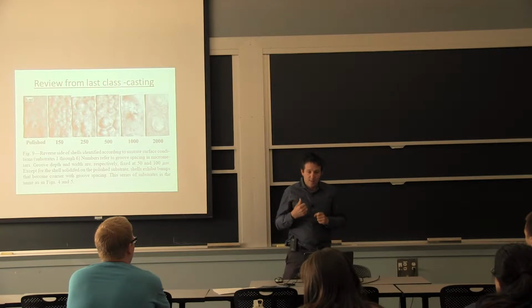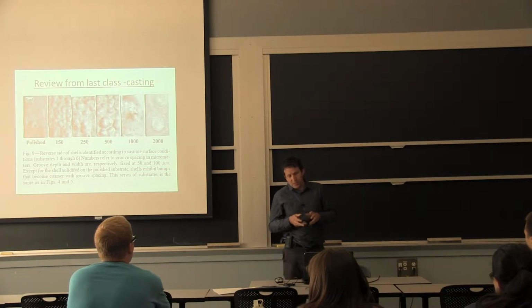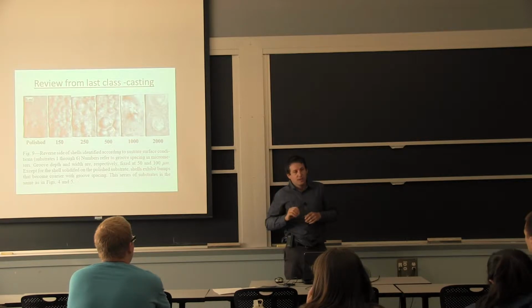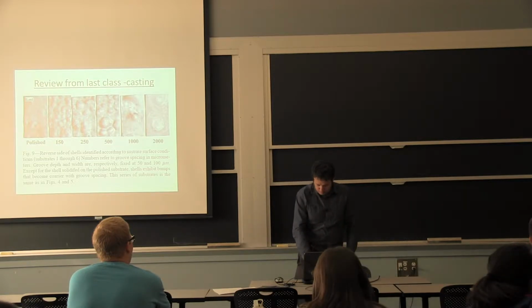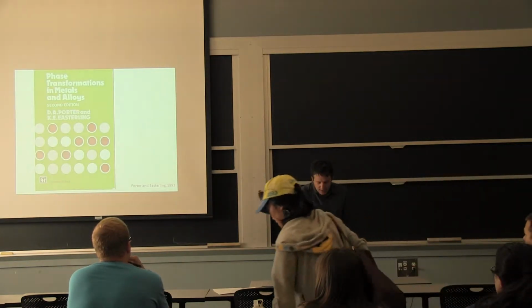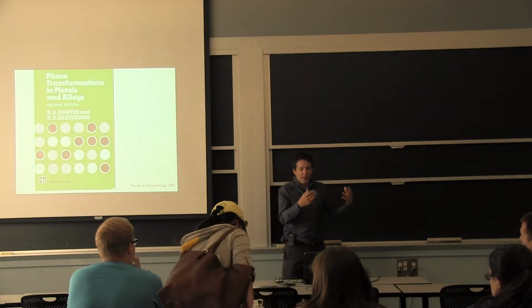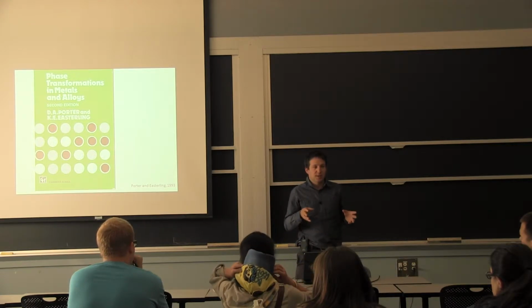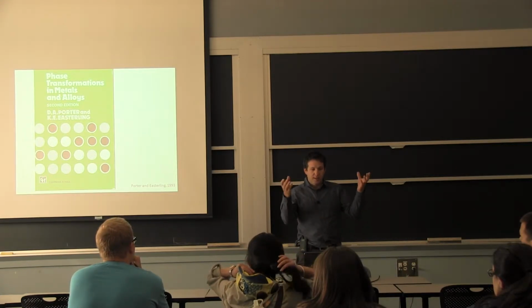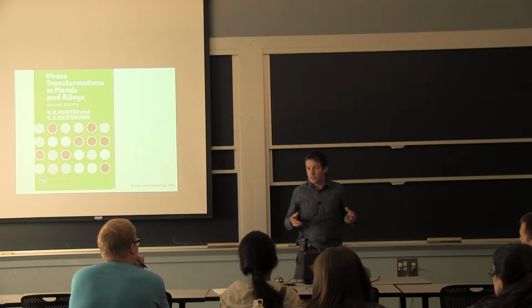In the example I gave last Friday, it was the roughness of the surface because the solidification was starting from the surface. But in a polymer in general, you can essentially say, I want to try to have as many initiation sites to end up with a very fine structure, and you work around that by adding particles essentially to your melt. So it can be useful. You can essentially make use of a lot of the natural phenomena, but what we're going to focus on for the next 15-20 minutes is what exactly is happening when I take the molten metal and I cool it down to solidify it to form a solid.